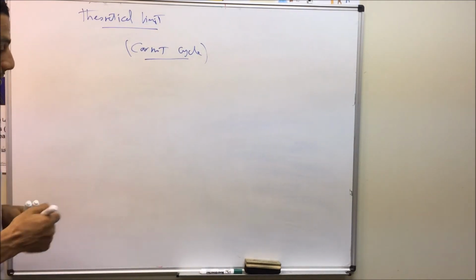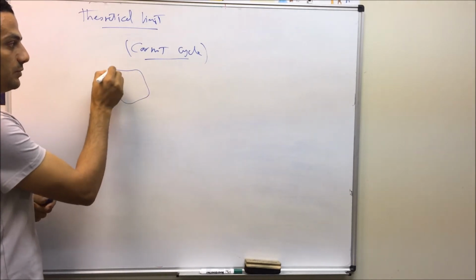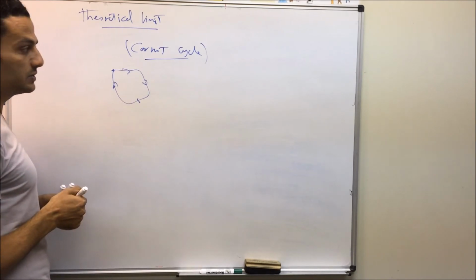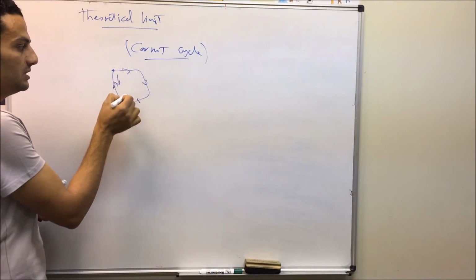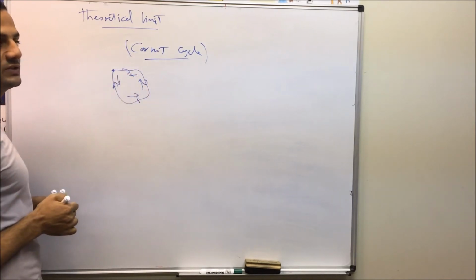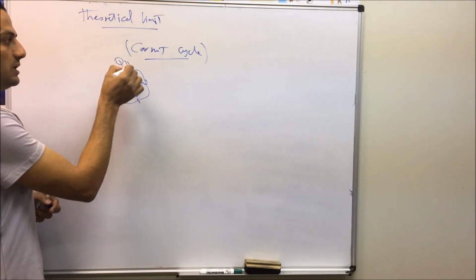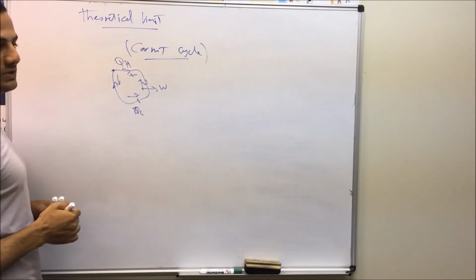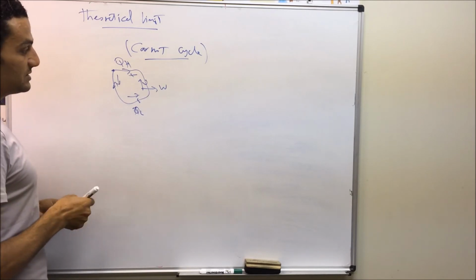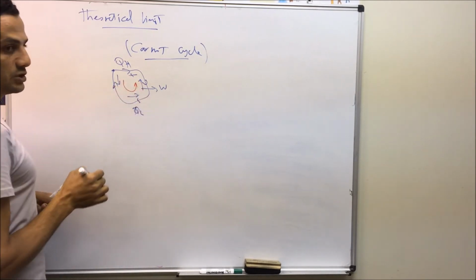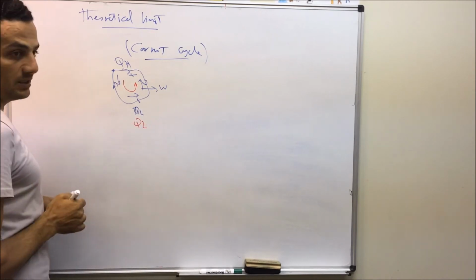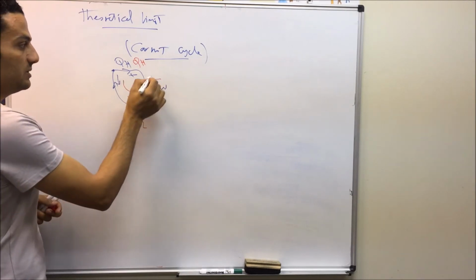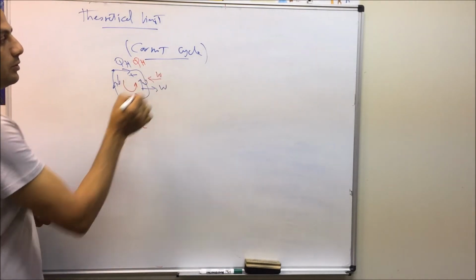The Carnot cycle consists of a set of processes proceeding in a certain direction, and all of these processes don't have any kind of losses within the system. Those processes can be reversed, or they can go in the reverse direction. In case of a heat engine, we add heat at high temperature, reject part of this heat at low temperature, and then we can have work out of this system. If the process is reversed, we add heat at low temperature, and we reject part of this heat at high temperature, and based on that we should have work input to the system.